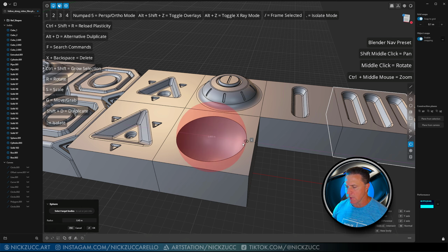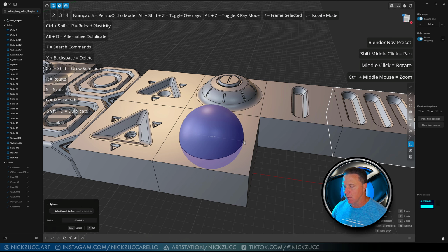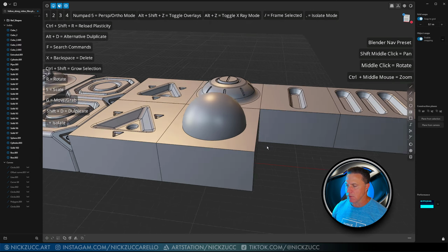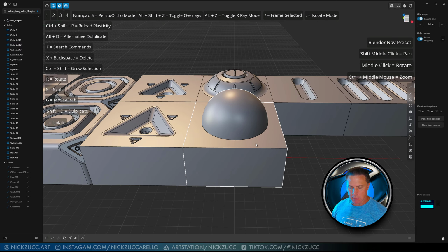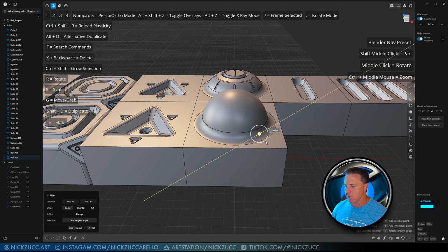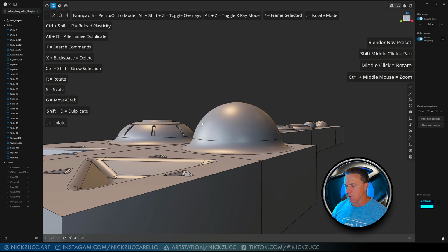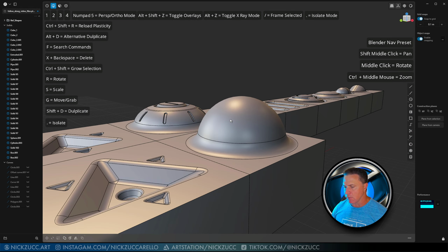And on this one, I'm going to actually use a sphere. Just click and drag this out, and then I will do Q like this, and let's get this a little bit smaller. So I'm just going to hold down Control and drag it in about here like that. Hit OK. So that should join the two of these together like this. Now I can tap 2 and then just do a really large fillet like this. And then the next thing I'm going to do is cut this off right around here in this area.